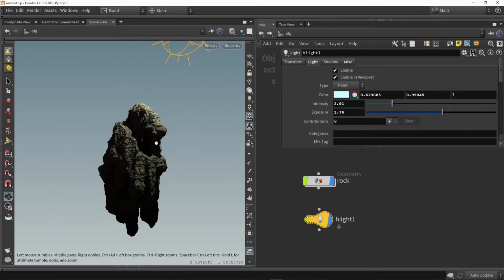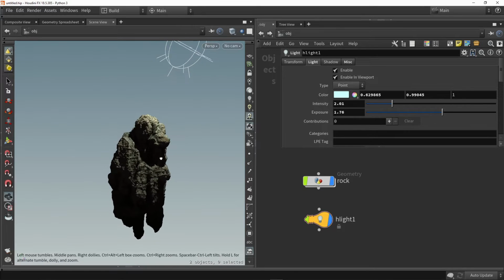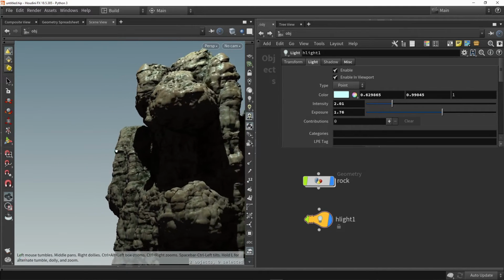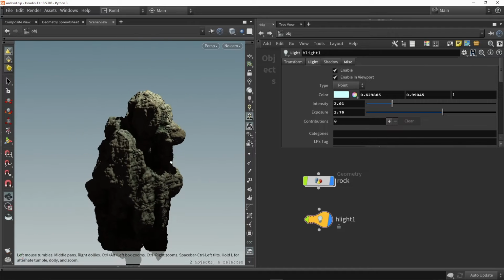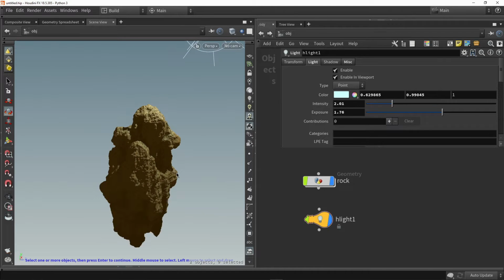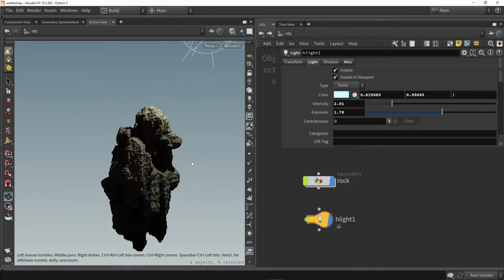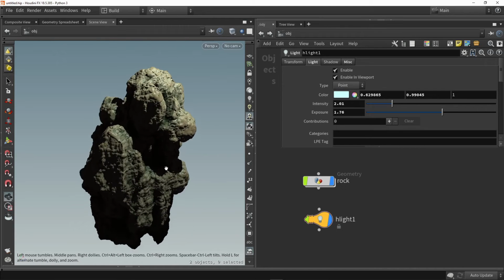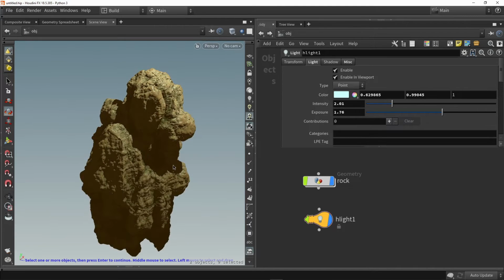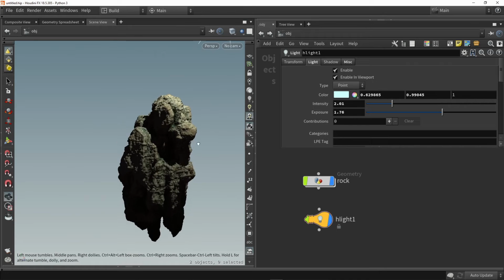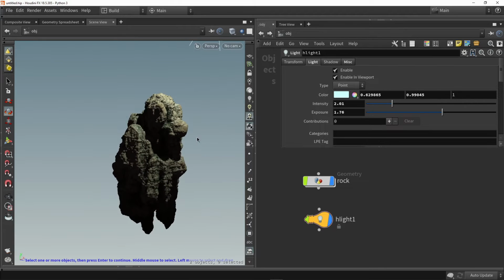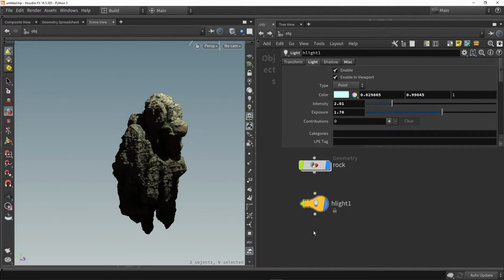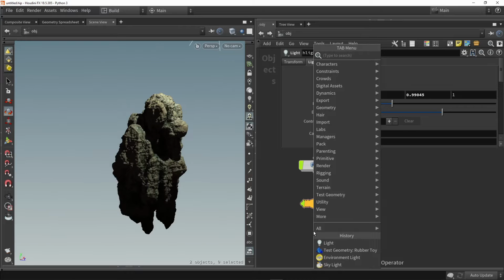Now, the other thing that I want to talk about is that our shadows are really dark. Normally, if you have worked with game engines, you will also include some environment reflection maps. So the light is not really bouncing here in our viewport. It's not like we have any global illumination here in real time. So we're gonna add an environment light.